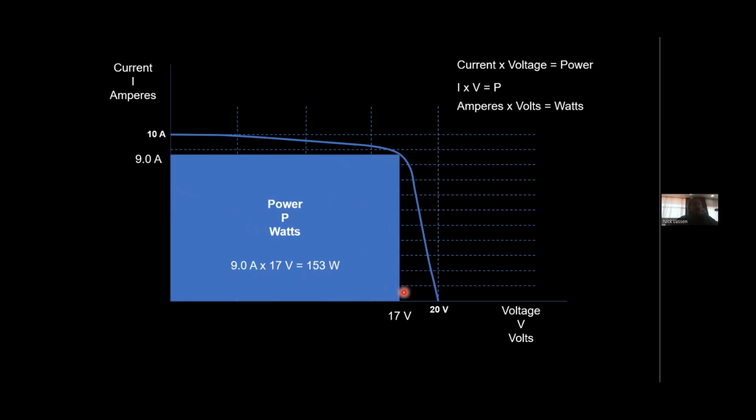So when you hear of MPPT, the maximum power point tracker, this is exactly what it is doing. It is using this curve. This curve is determined by the panel. And the MPPT is trying to always find the balance that will give you the most watts. Because when you change the current and the voltage, you're changing the watts.